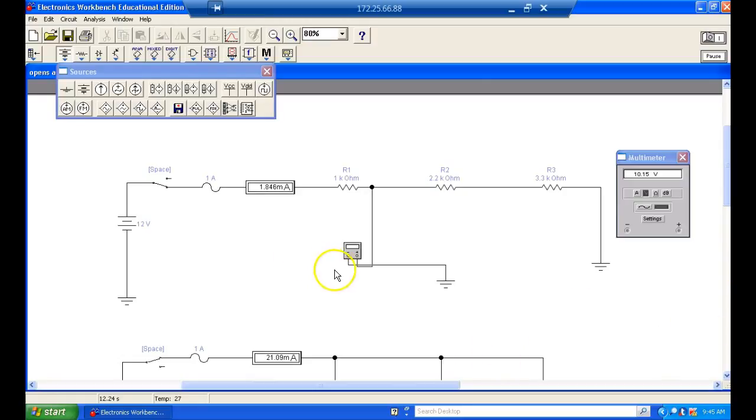And we can measure with our meter. This lead right here, this will be what we call our black lead. This lead does not have to be connected to circuit common. We can literally come up here and connect it across something, and we can measure the voltage drop. Now here I hooked my meter backwards. Well, not backwards. I have the minus, the black lead, towards the positive, and I have the positive lead towards the negative. So my meter reads negative. It's not a negative voltage. It's just the way I have the meter. So that resistor is dropping 1.8 volts.